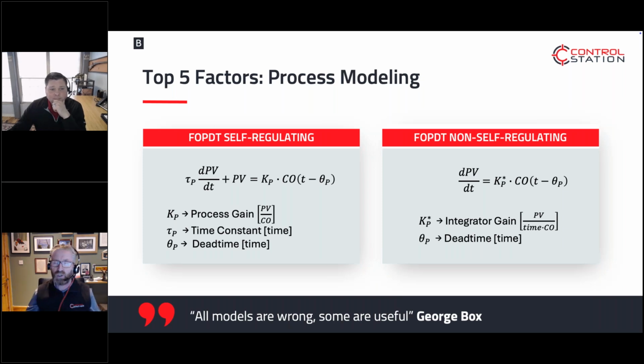It can, but it's that delay from when we make a change till when we see the change. If that instrument is poorly located 10 meters or 50 meters down the pipe, that's dead time, and you're never going to be able to accurately control. This is the killer of good control, perhaps, is a good definition of it.